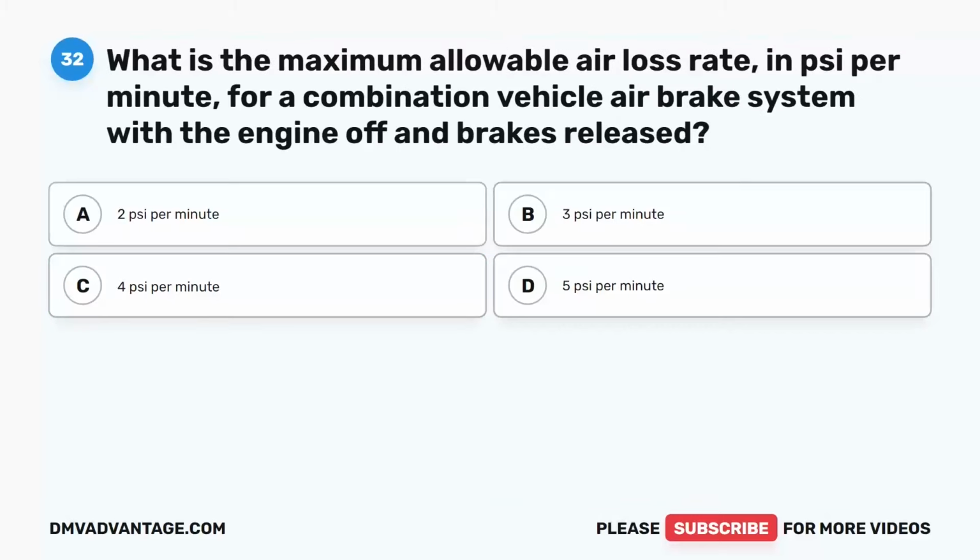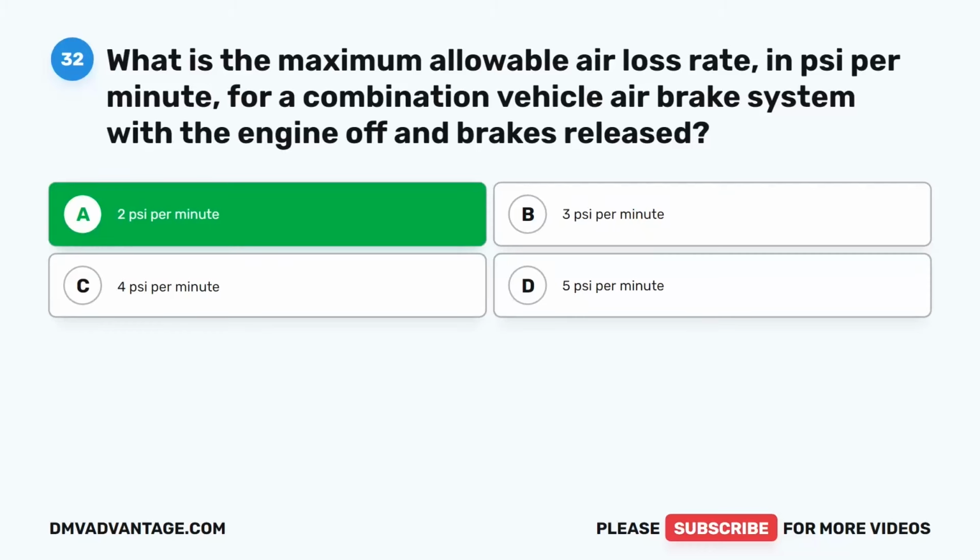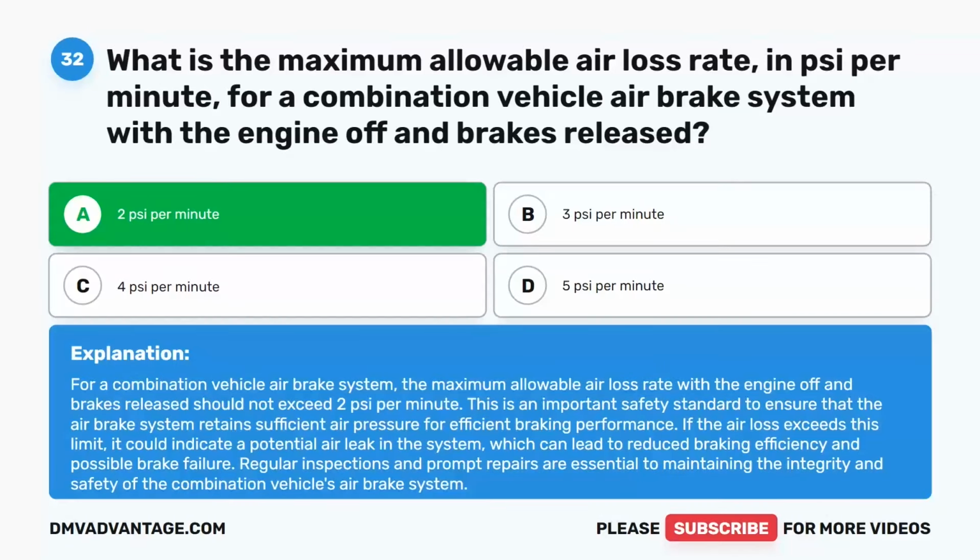Question 32. What is the maximum allowable air loss rate in PSI per minute for a combination vehicle air brake system with the engine off and brakes released? A. 2 psi per minute. B. 3 psi per minute. C. 4 psi per minute. D. 5 psi per minute. The correct answer is A. 2 psi per minute. For a combination vehicle air brake system, the maximum allowable air loss rate with the engine off and brakes released should not exceed 2 psi per minute.